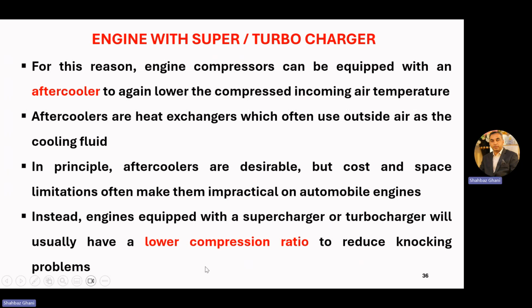Instead, engines equipped with a supercharger or turbocharger will usually have a lower compression ratio to reduce the knocking problem. So in order to cater for this knocking problem, which is self-ignition of the air-fuel mixture, we use a lower compression ratio.